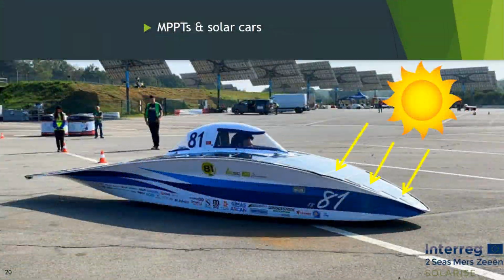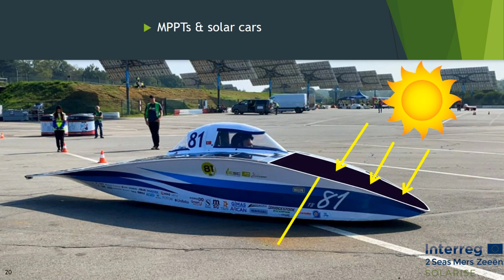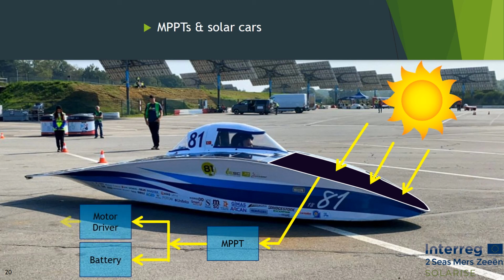Solar cars are vehicles which generate the energy needed for traveling from the sun using photovoltaics. Since the surface area of the photovoltaics of these cars is limited to 4 square meters of silicon solar arrays in the regulations of most solar car challenges, the total power of the photovoltaics on these cars is generally around 900 watt-peak. Generated energy is sent to a battery pack and motor driver using MPPTs. During travel of the vehicle, the source and the load sides vary instantaneously. For acceleration, they also have a battery pack which is limited to 5 kWh.